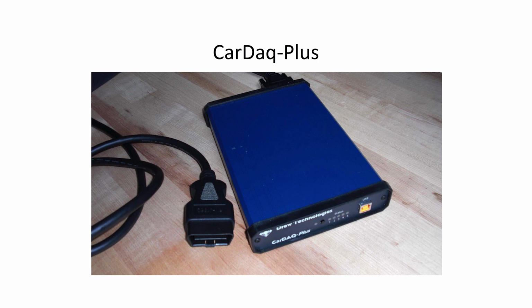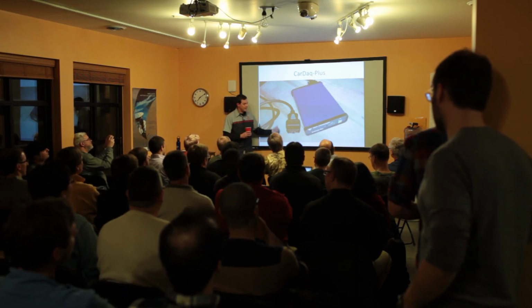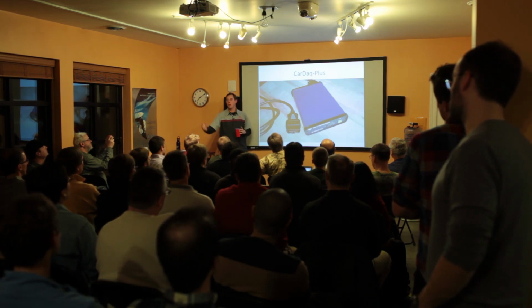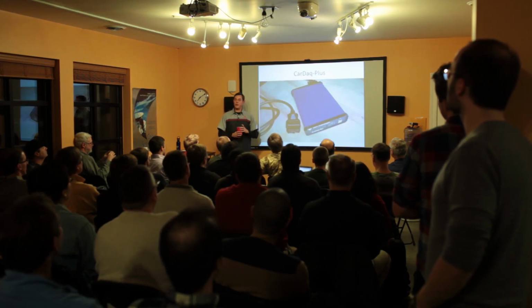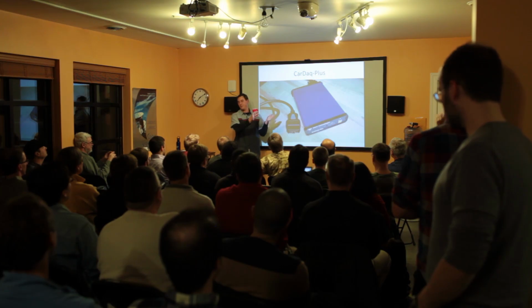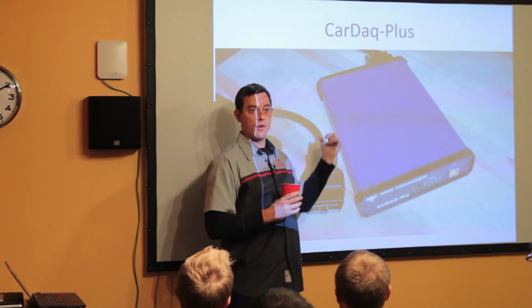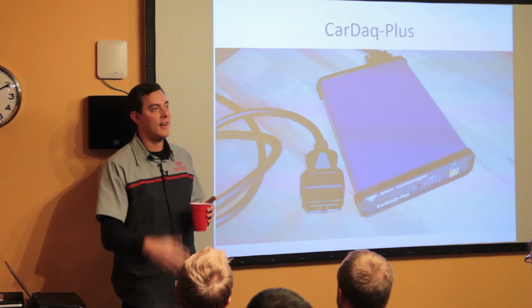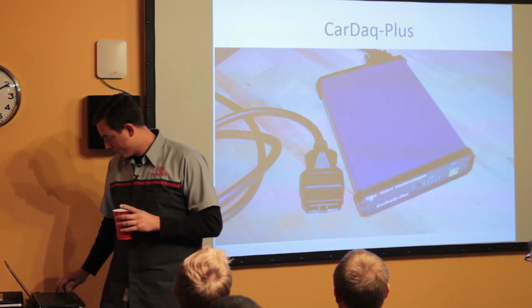Another thing we use, especially for the Toyota, is a thing called a J2534 pass-through device. When you go to a dealership, they basically hook one of these up, and this machine hooks to your computer, and then they use mechanic software to pass messages back and forth, update. The cool thing is, what we did is buy an OBD2 splitter, just wires that split it out into a Y, and we would use this to, say, update a firmware. And then we would have our sniffer on the other side. Since it's broadcast, we saw the traffic, and you can use that to figure out how they work, right? A little bit of network reverse engineering.